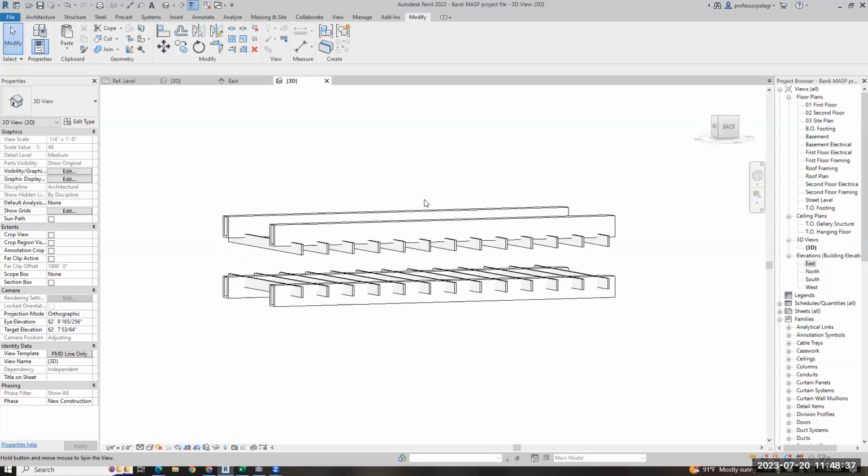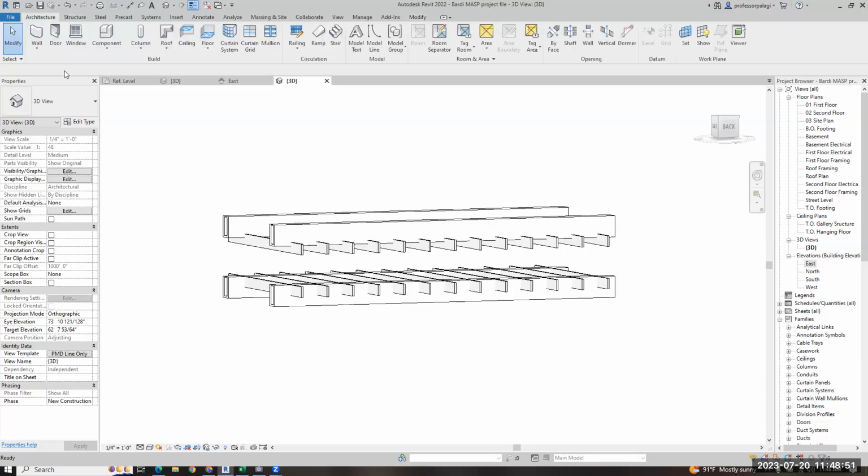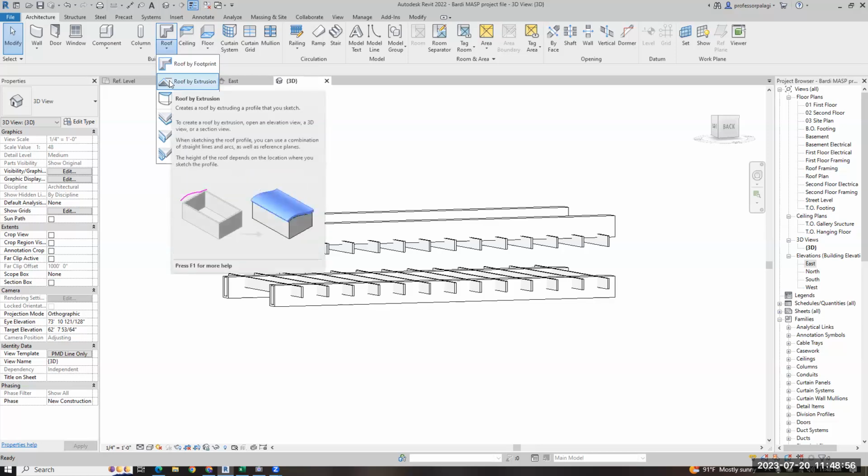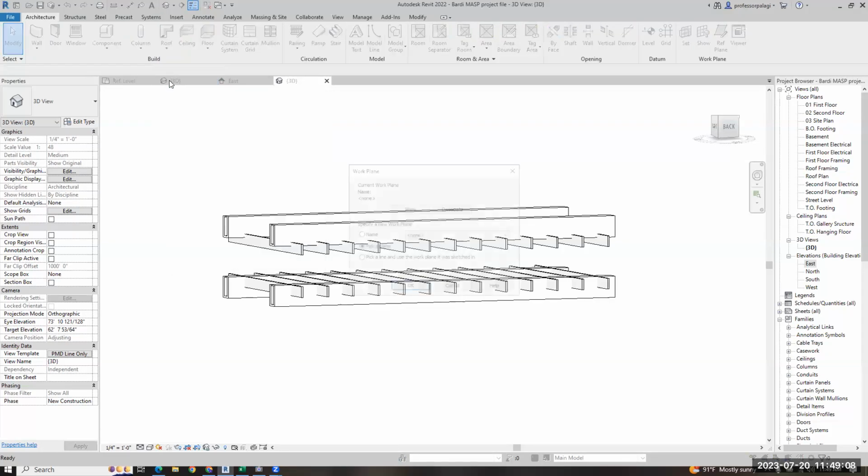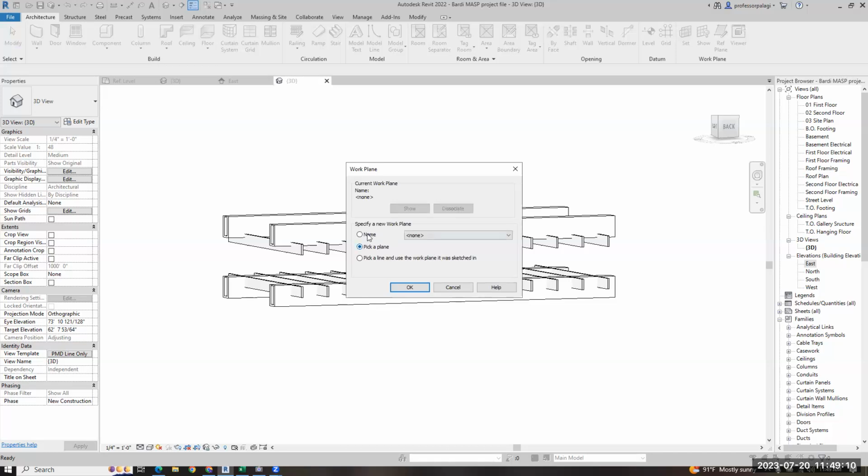I want to draw a roof, and this is why I drew those when I named the front and side as planes. It was a cheat because I know that I like to draw roofs using profile of extrusion. Most of the time I'm doing a roof, it's a shed or even if it's complex, it's one direct. Even if it's a pitched roof, even if it's a split pitch roof, you can still do it by extrusion. So, but it asks what do you want to use?